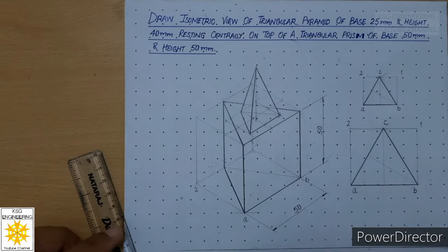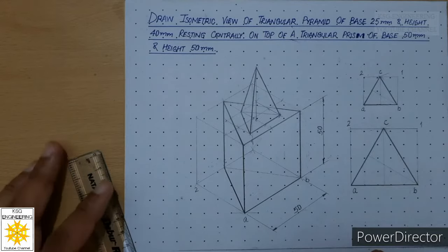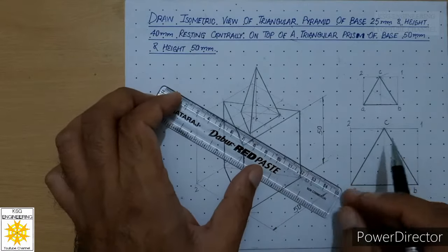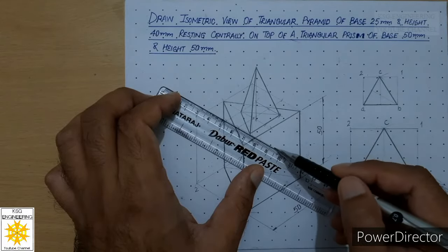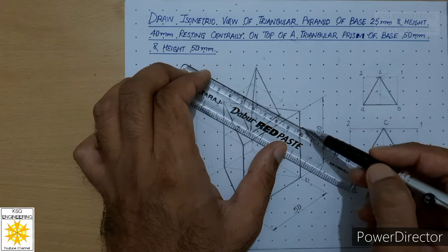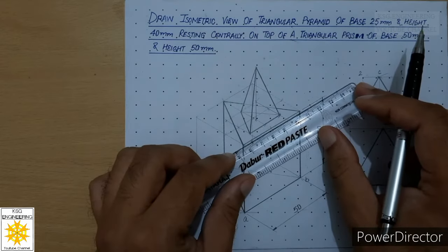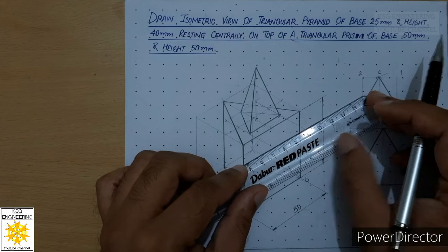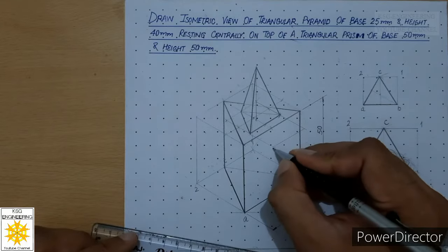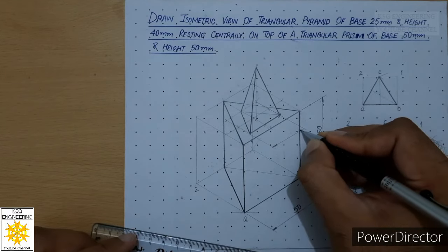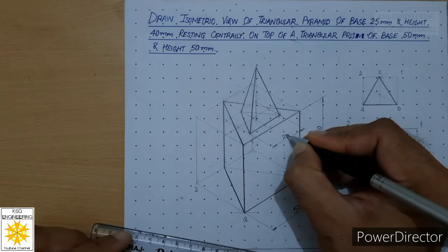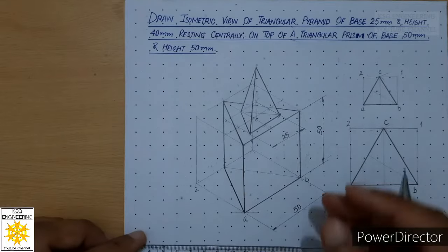Now after that, we will place dimensions for this pyramid. So let us place the dimension for this edge. So place your scale aligned with this isometric line. Leave a 1 millimeter gap, continuous thin line. Then place your scale aligned with this isometric line. Leave a 1 millimeter gap, continuous thin line. Align your roller scale with this edge, roll back by around 20 millimeters and draw a thin line over here parallel to this isometric line. Add closed filled arrowheads on both sides. So over here we will mention its base as 25 mm. Then after that we will place its height.